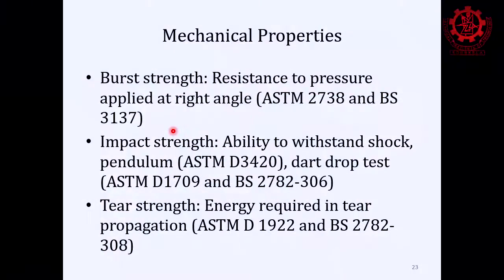So I had to really struggle, and if you apply very high force, then if you shake a little bit, the powder just falls. So it's a bad packaging, bad design. They could select a film or polymer which has good sealability but has a low tear strength, right? So you can easily tear. So many of these pouches, sometimes chips bags, we really struggle to open, simply because the polymeric films used in them have very high tear strength. So the knowledge of tear strength in different polymer materials will help you select for the appropriate application.